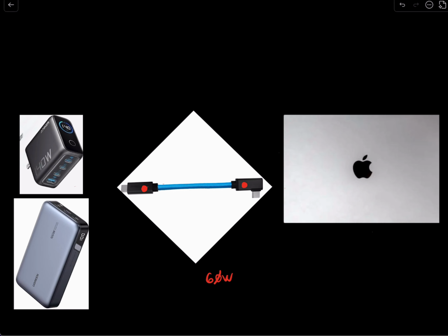You see, when you connect the USB-C connector to your laptop, immediately after it there is a chip called the PD, or power delivery chip, which is the one that initiates that protocol, telling me how much power you can deliver so I can charge my battery faster, right? Otherwise, if the power you are supplying is below what the laptop consumes while operating, you're draining the battery even though you are connected, and you don't want that.